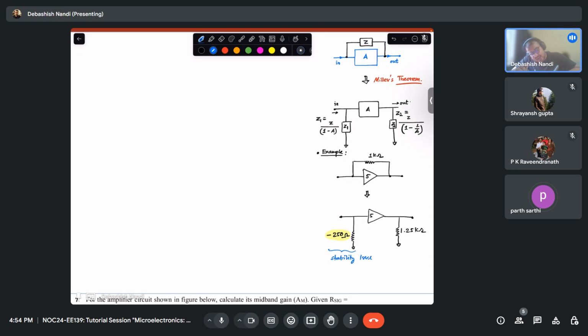To mitigate that, you add other resistances to stabilize the circuits. So always remember, whenever you are probing some negative resistance in your circuit design in future, there is a gain from that end to the other end. In amplifiers, on the input side, you get negative resistances because of the Miller effect.